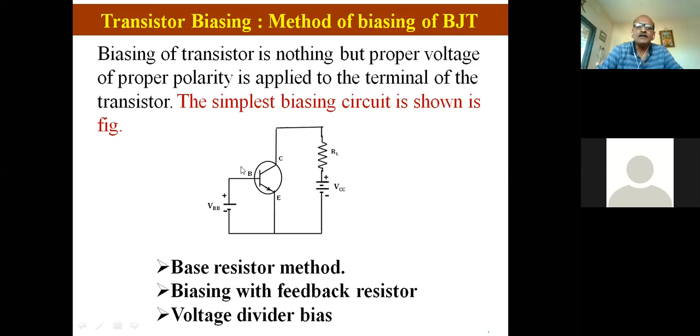Similarly, to the emitter junction becoming forward biased, the collector junction can be made reverse biased. How can we make the collector junction reverse biased? Positive voltage is given to the collector. The collector is N type and positive voltage is given to the N type material.